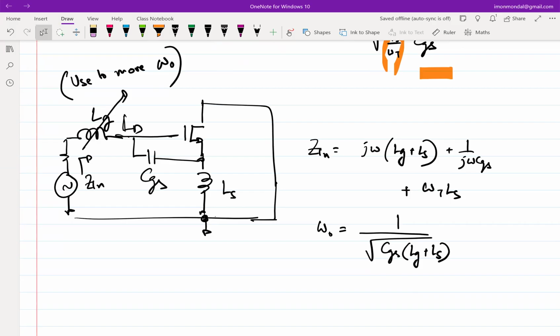So if we had put an additional inductor here, then obviously this would have changed, and that we don't want to do. This is not an RF principle, this is any design principle. The moment you have one component which varies multiple things, try to fix that component and don't change it, then try to introduce another variable which changes the other thing. I'm pretty sure in two-stage op-amps you also see the same thing. If you start off with DC gain, you have a problem. You start off with UGB, fix the GM, then you do whatever you want to tune the DC gain.